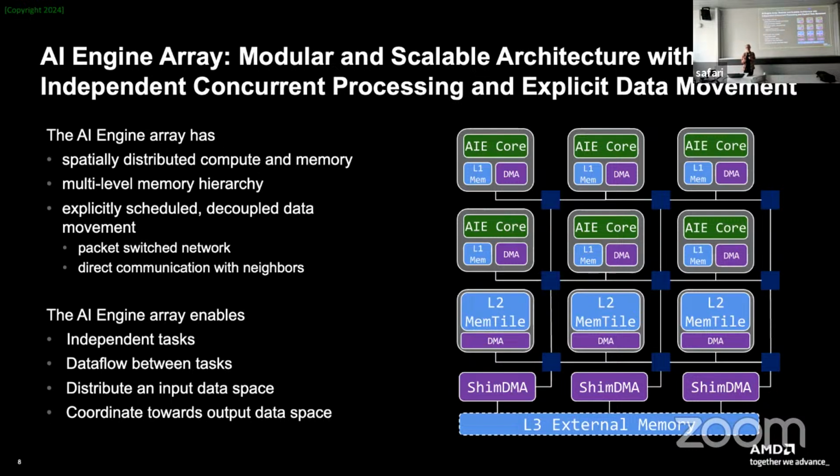Though, for completeness, our software stack currently mainly focuses on analyzing things statically at compile time. And also each memory is a scratch pad, so again, each level. Yeah, that's very important to realize. That's why we use the terminology explicit data movement. And that's why I mentioned now multiple times, a compute tile can only see and address its own memory.